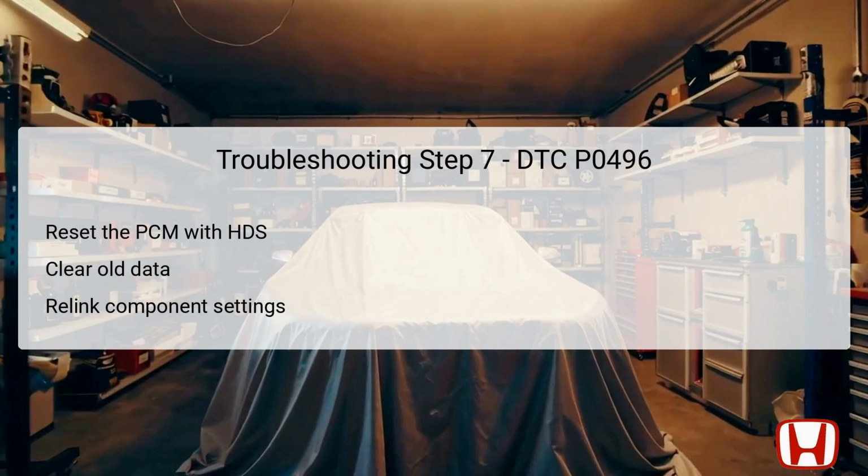Resetting the PCM is a vital procedure as it clears the old data stored in the system and allows it to relearn the new operational parameters associated with the EVAP canister purge valve. Without this reset, the PCM may continue to trigger warnings or maintain old fault data that is no longer applicable.